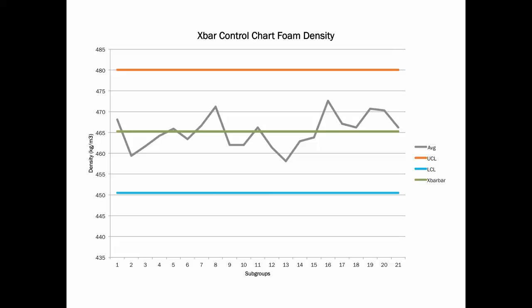or the design specifications. The upper and lower control limits are calculated from a formula that uses subgroup averages from the process. They don't use specifications or tolerances at all in their calculations. It is simply a measurement of the process.